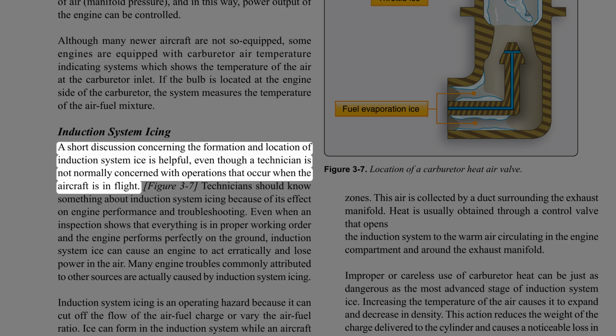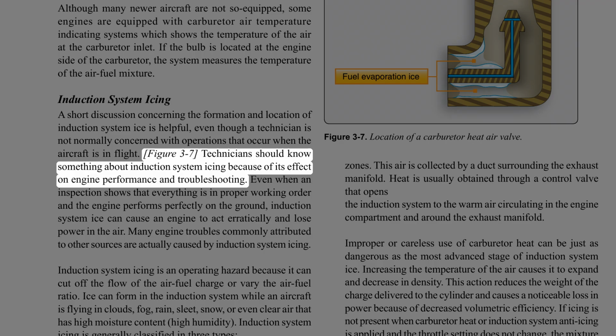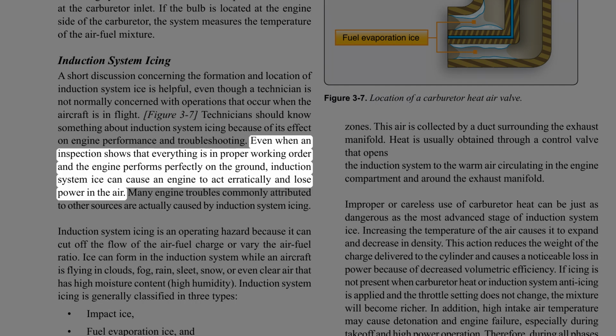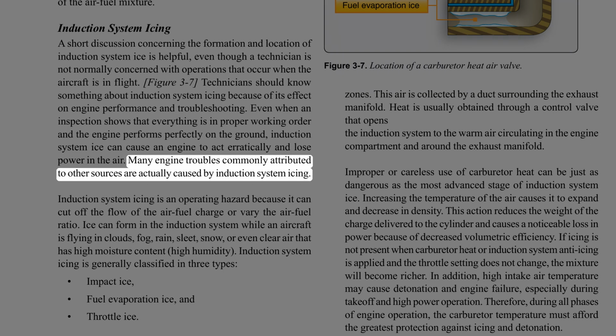Induction system icing. A short discussion concerning the formation and location of induction system ice is helpful, even though a technician is not normally concerned with operations that occur when the aircraft is in flight. Figure 3-7. Technicians should know something about induction system icing because of its effect on engine performance and troubleshooting. Even when an inspection shows that everything is in proper working order and the engine performs perfectly on the ground, induction system ice can cause an engine to act erratically and lose power in the air. Many engine troubles commonly attributed to other sources are actually caused by induction system icing.